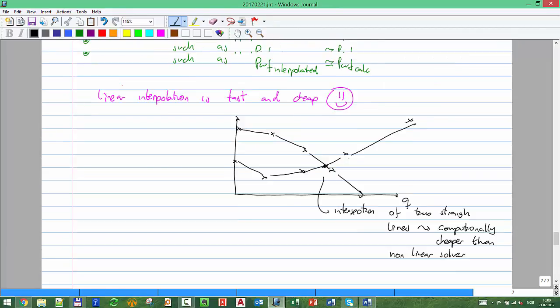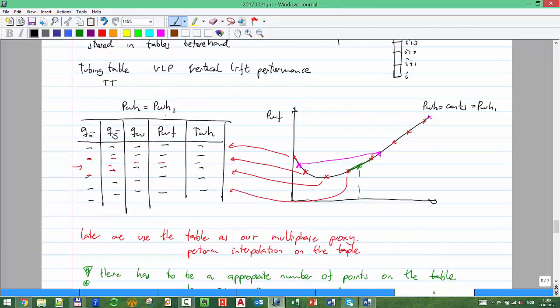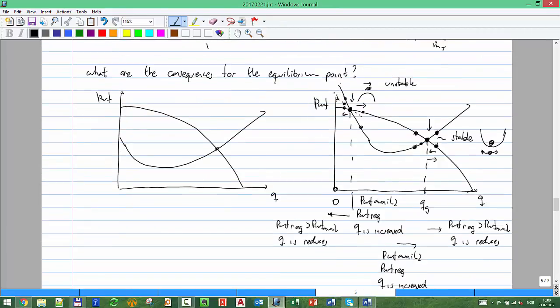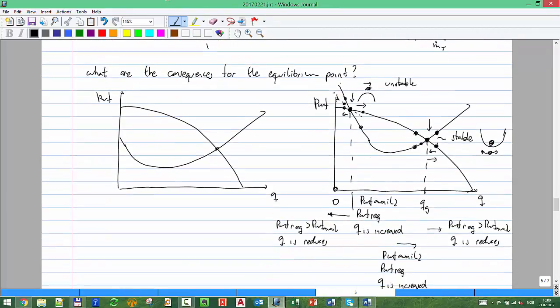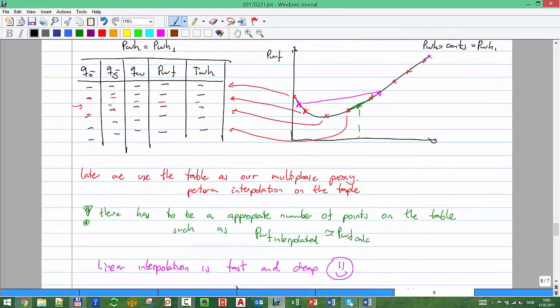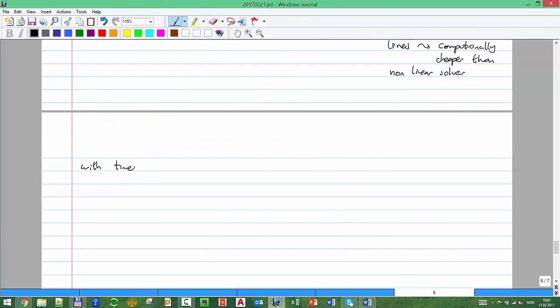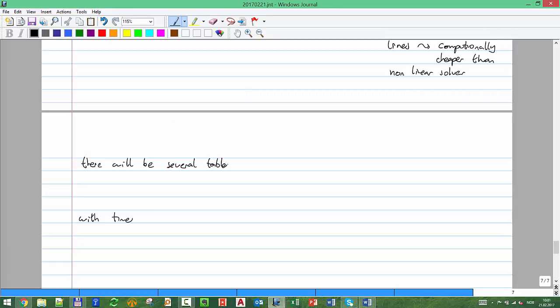one more thing is that in that case, if we are sure what the wellhead pressure is, that we have it, but really if we have, for example, a flow line, if we have the system that we showed before, then the wellhead pressure won't be constant, but will also be a variable. So you usually have several tables for each wellhead pressure, for different wellhead pressures.